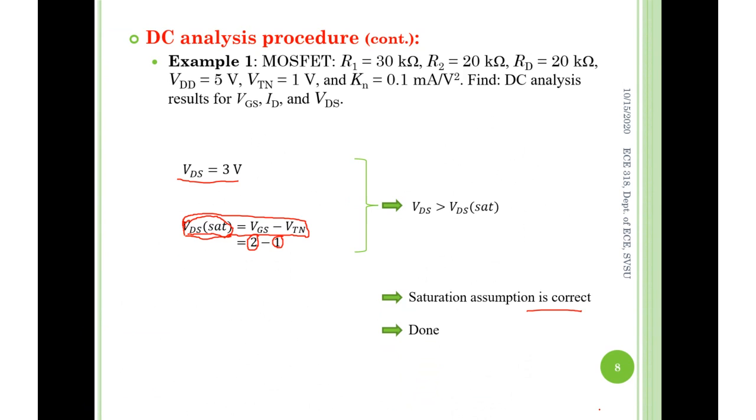DC results. Remember, in the diode circuit, same idea here. The DC analysis always goes first, because your AC analysis requires a DC analysis result. Just like the discussion we just had with Connor. How much AC swing and gain you can obtain is up to your DC operation point, where you're located. Absolutely matters.